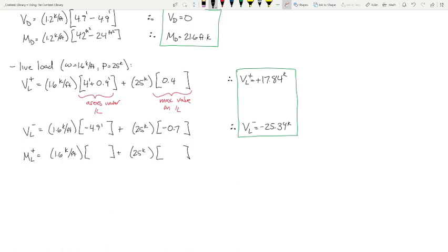What's the value right here for the distributed load? The area under the influence line. What area do we use? 42. And again, if you want a unit, it's foot squared, but it doesn't really matter because everything's consistent. And the 25 kips, what was the value there? 4.2.